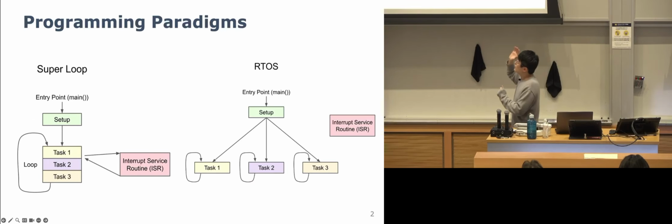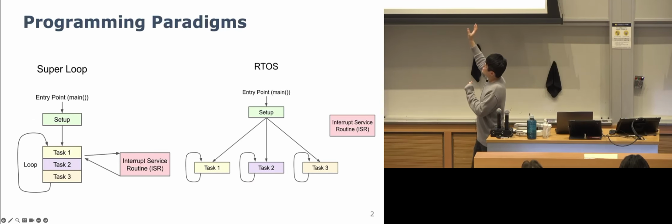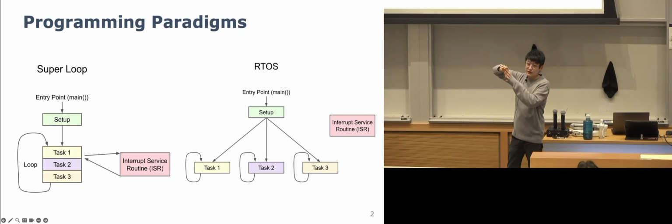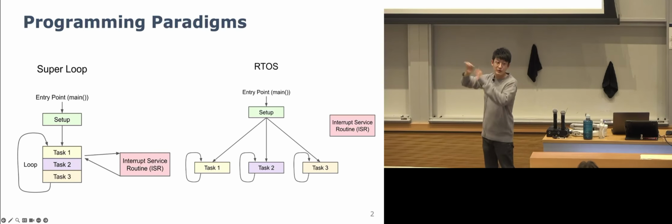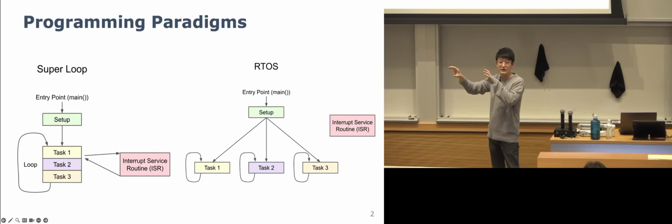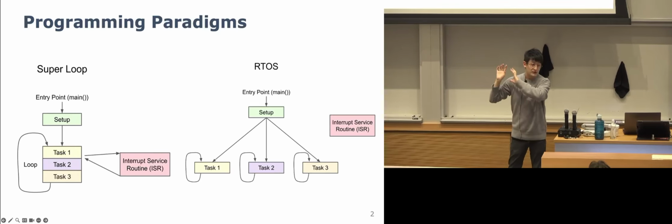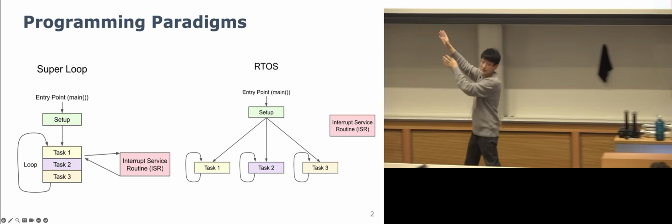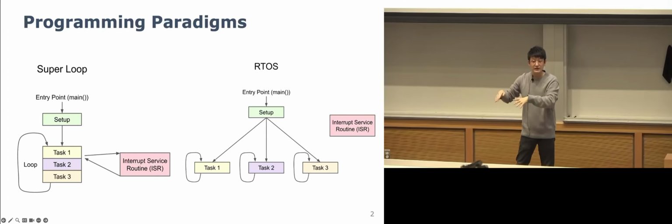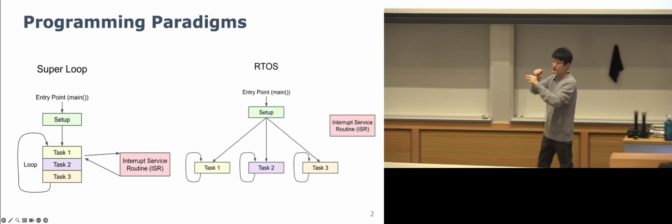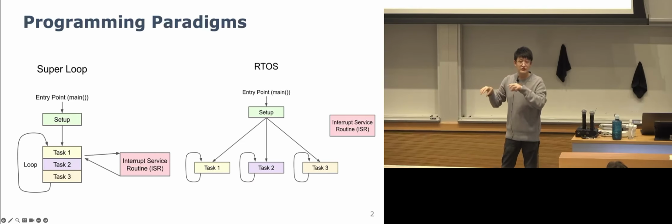And then whenever it needs to get to another task, the register values get pushed into the stack that task was allocated, so that it can switch to another task by popping back the values on the stack for that one. So in a way, they're able to be dynamically ordered. Instead of normal interrupts, which have to be executed in sequence when you pop back or enter, here you have the freedom of randomly jumping inside each of the tasks.